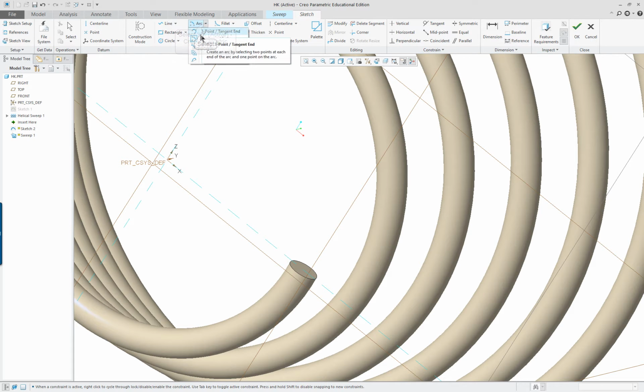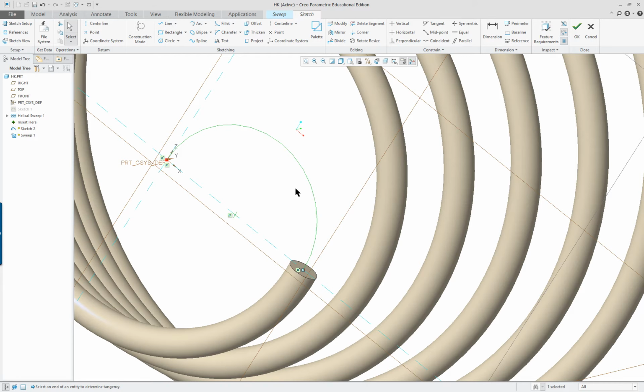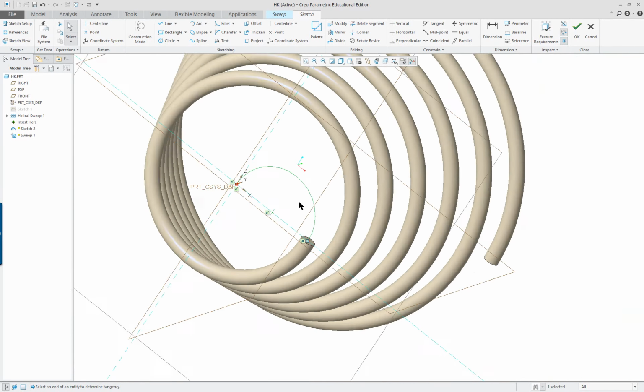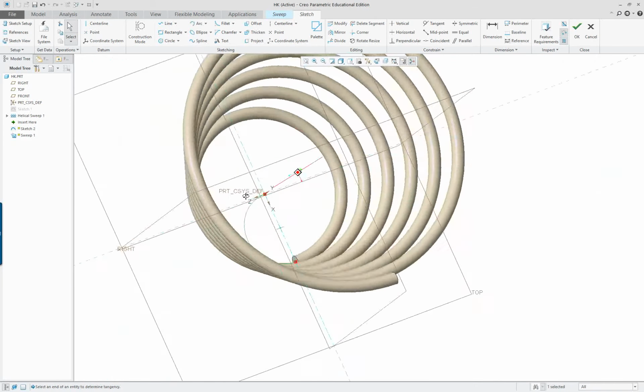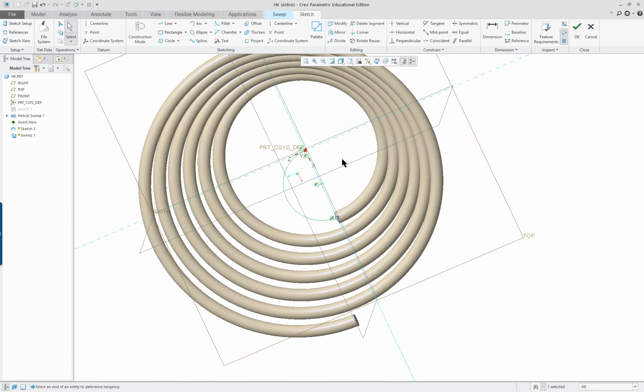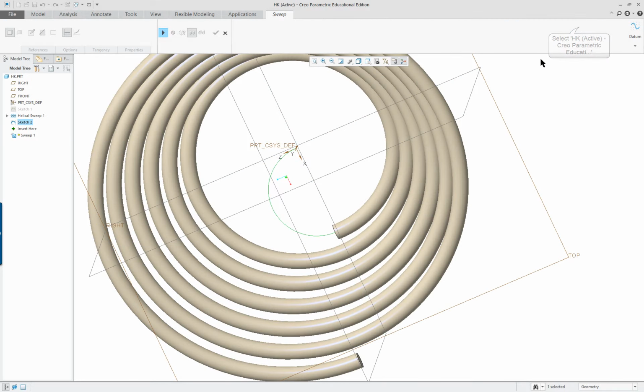Now I'll click, and let's say, well, you know what I'll do? Let's try a different type of arc. Let's try the 3-point. Let's pick here and pick the origin and pick again. So that works a little bit better, as you can see, because I've got it locked in and there's no dimension, which is nice. So check and continue. We want to resume, and we see our arrow is over here, and we really want the arrow to start at this point. So I just clicked on it.